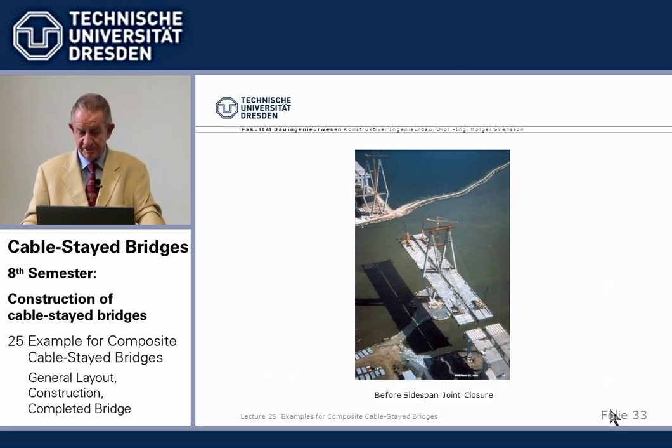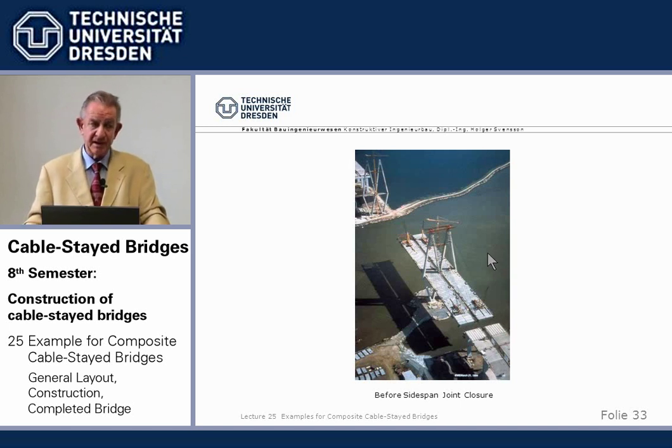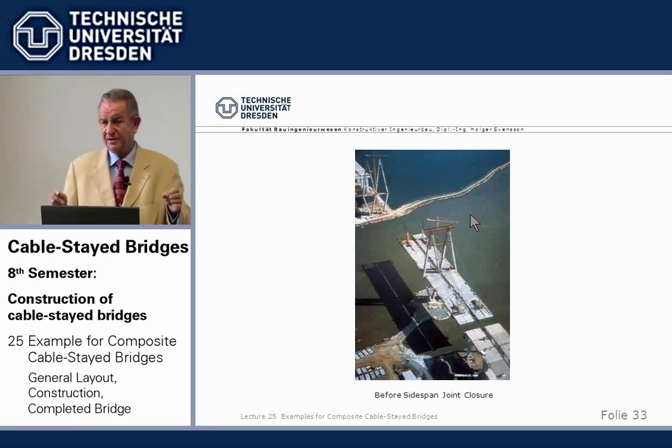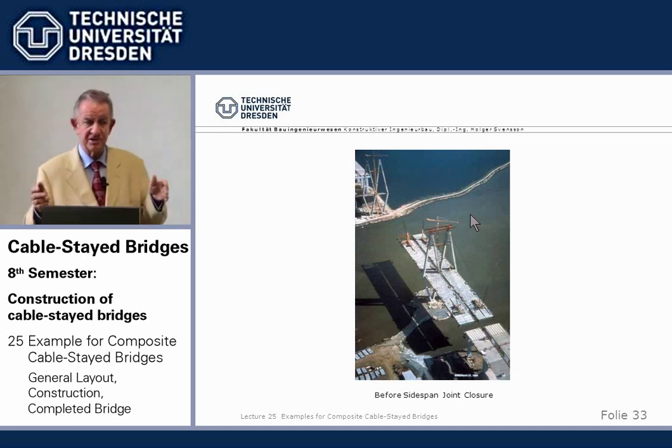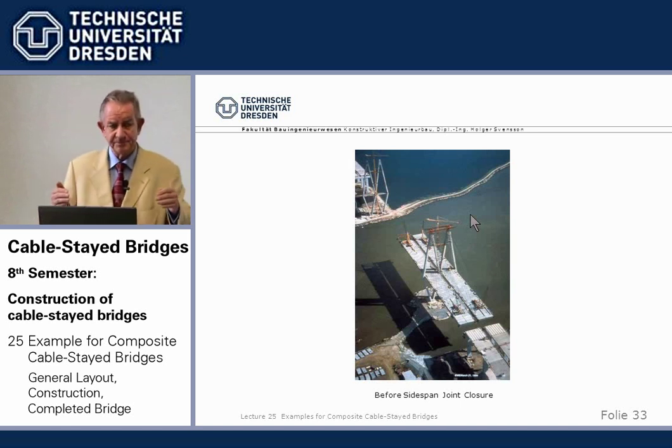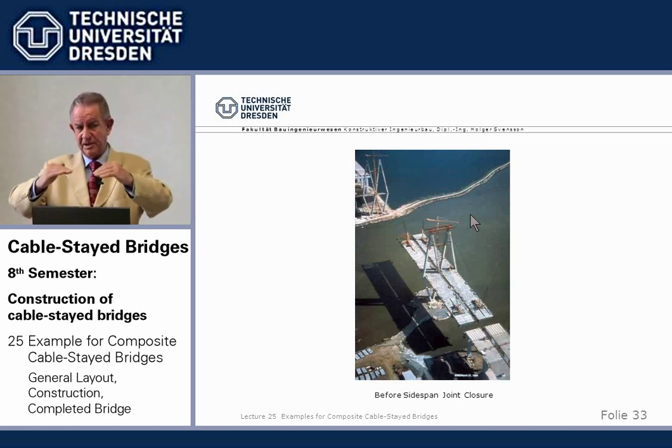Here we have then the situation that we have free cantilevered the two, and we are ready to close the side span joint. I may add that, of course, it was a decision, shall we first build the first bridge complete and then the second beam? But one reason why we built it in parallel was that aerodynamic investigation, especially wind tunnel testing, showed that when we have two beams side by side,